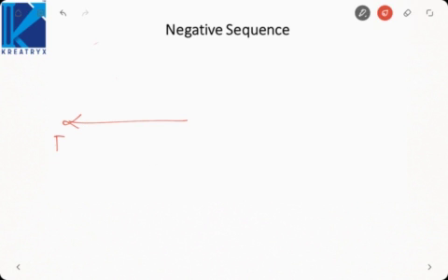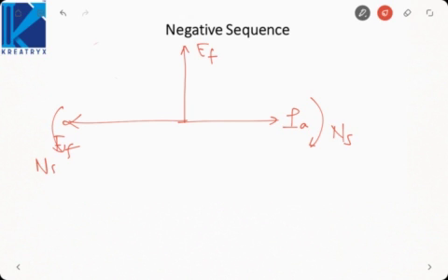Okay. So now if we see in terms of the phasor diagram, this is my field MMF, this is EMF, this is IA, but now it is rotating at ns like this. What we can do instead is assume that this has 0 speed and this rotates at 2ns with the relative speed. Right now it is lying along the d-axis, but after 90-degree rotation it will lie along the q-axis, then again along d, then again q, then again d.